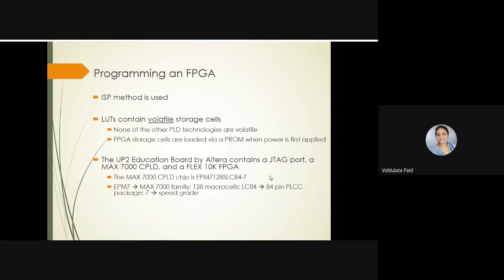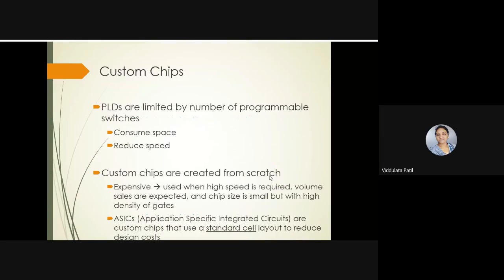Okay. Now if we go for custom chips, that means chips which are designed as per the application, that are ASICs or system on chip. PLDs are limited by the number of programmable switches, because of which they consume space and reduce speed. That is one more disadvantage of PLDs.